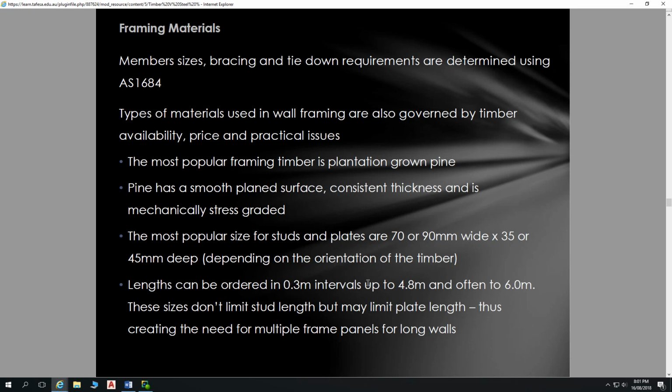So it's about going through those things, thinking about our uses of timber for being economical in that specification of timber. If we specify sizes that are odd, yes, you can end up having some fantastic architectural results from that, but typically it's going to be far more expensive because our wastage is more.